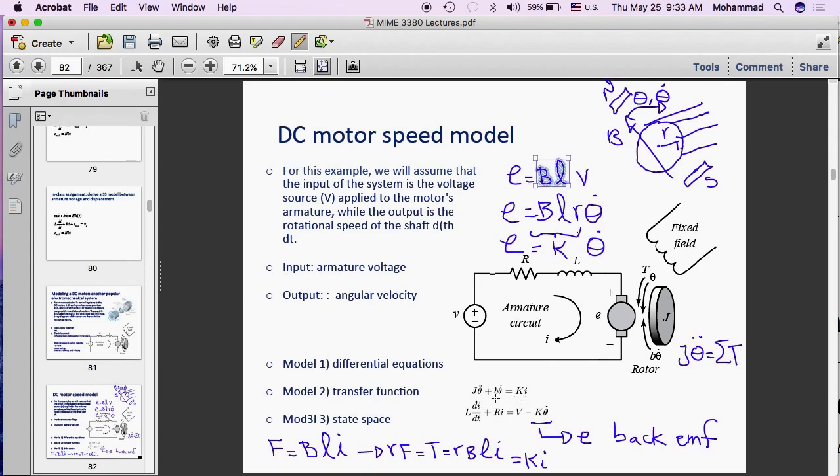It basically says there are two externally applied torques. One of them is K times I with a negative sign. Let me include the negative sign. So it is equal to minus K times I. And the other one is friction, also with a negative sign, so minus B theta dot. If you bring B theta dot to the other side, I apologize, K i is positive, it is driving the circuit. I made a mistake. So this should be positive.